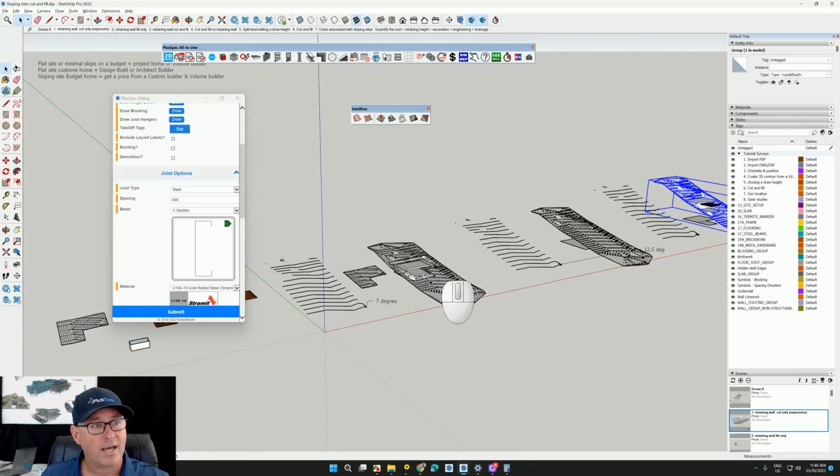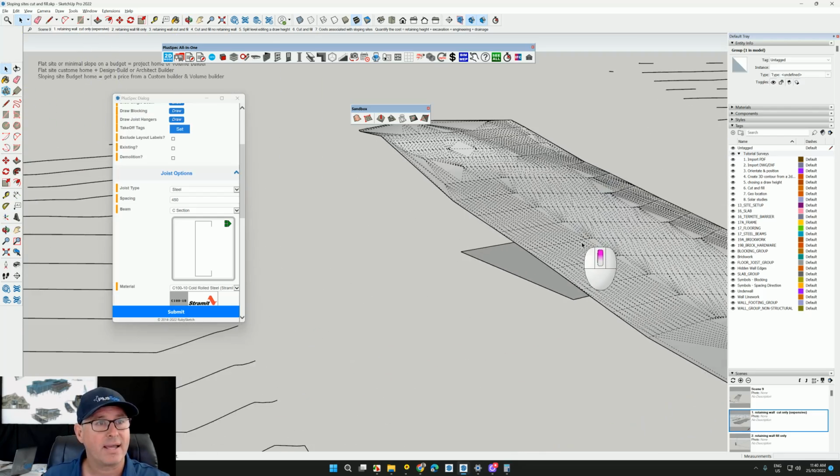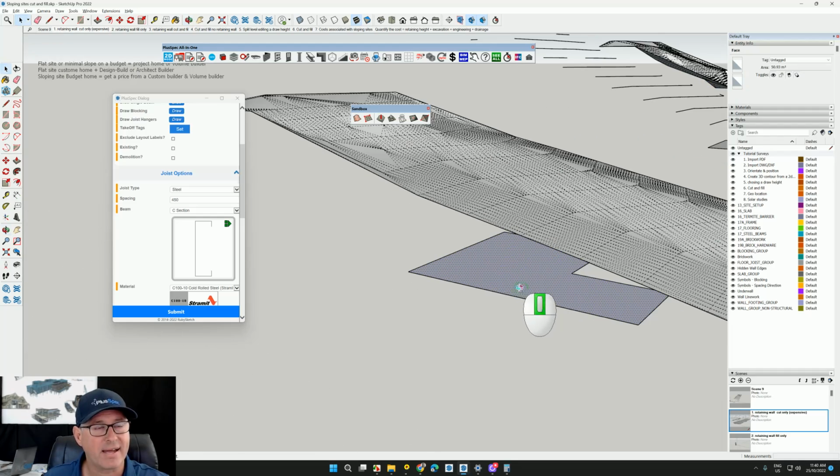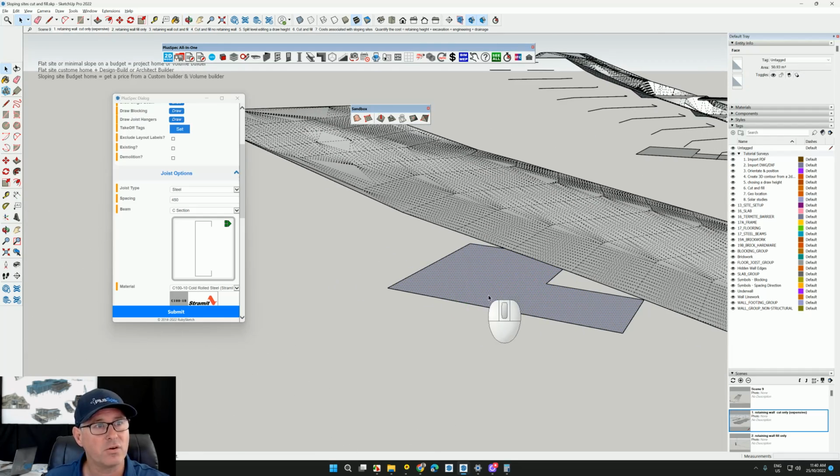I guess there's one other thing I could quickly talk about, which is what happens when I want to buffer around the outside of here. You'll notice when I select this face and choose my stamp tool, down the bottom here it says offset. Now if I wanted this one to be a 2 meter offset, I would have to type in 2000 millimeters